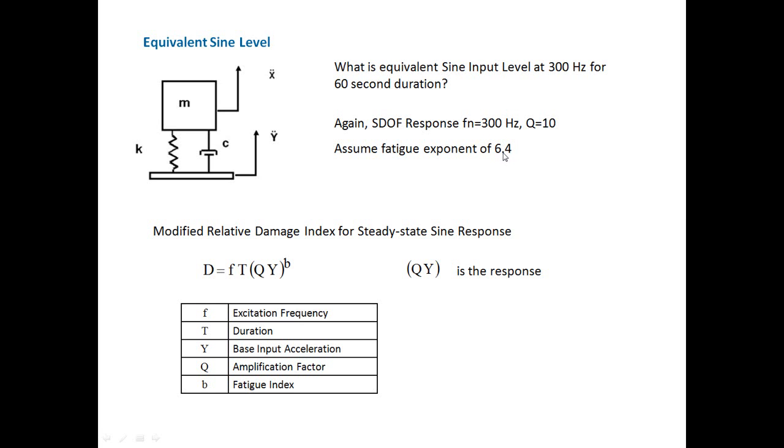And it turns out that doing the rainflow calculation for a sinusoidal response is almost trivial. We do not need Endo and Matsuishi's algorithm. We don't need that ASTM spec. It's just really intuitively clear how to calculate the rainflow for a sine input.